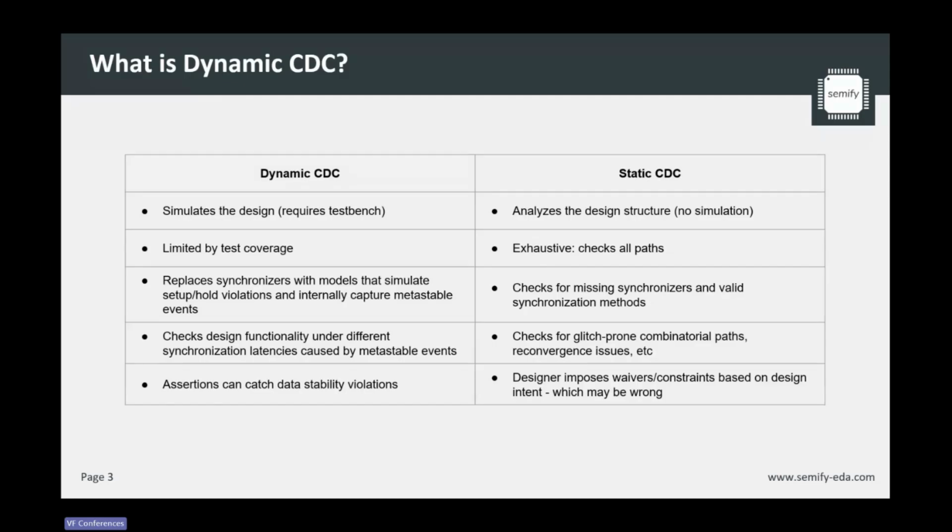We'll talk a little bit more about what all that means in some of the next slides. But in short, some of the differences between dynamic CDC and static CDC is that dynamic CDC requires a test bench and a simulation to actually run, whereas static CDC just analyzes the design of your RTL to check for things like missing synchronizers or reconvergence issues there.